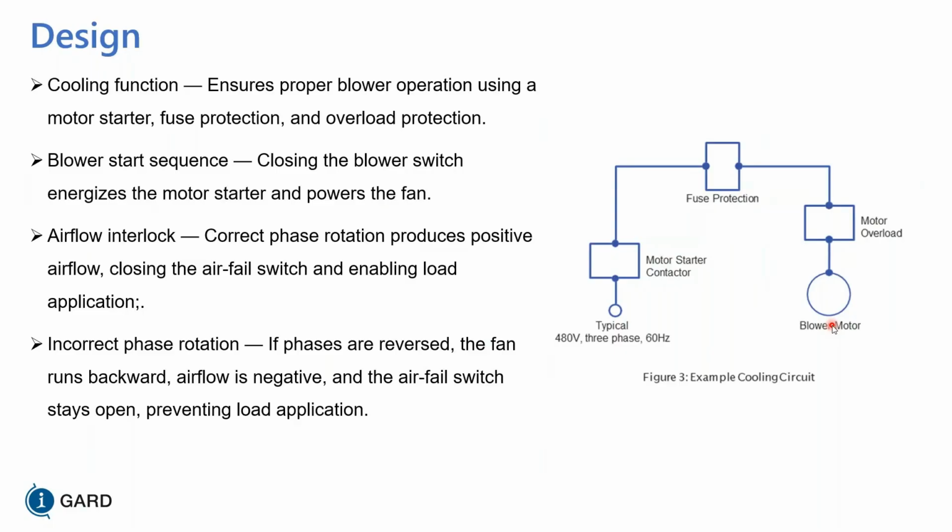We obviously have backup protection on the blower because you want to have airflow, make sure that the air is blowing across the resistor, and pressure differential across the resistor to make sure that everything is working properly. And sometimes you can have these things outside, so we'll have automatic dampers on them, so they'll close automatically, open automatically, and start to function.